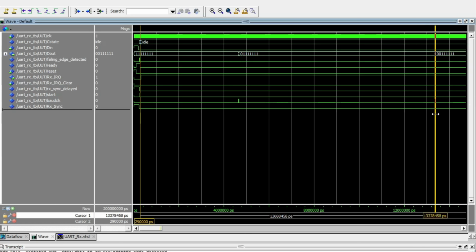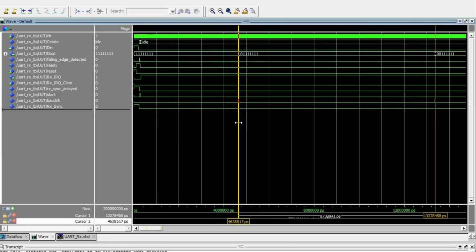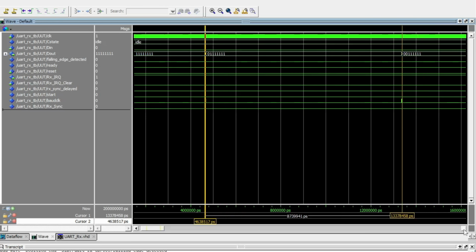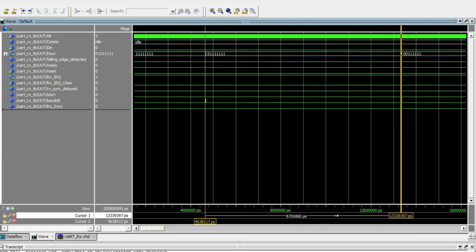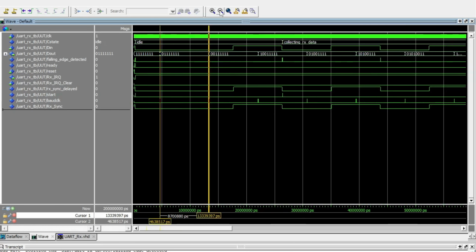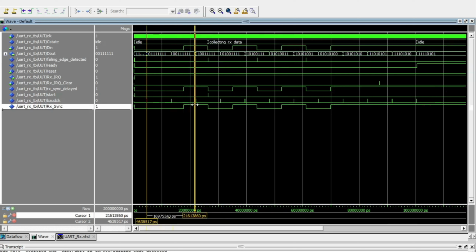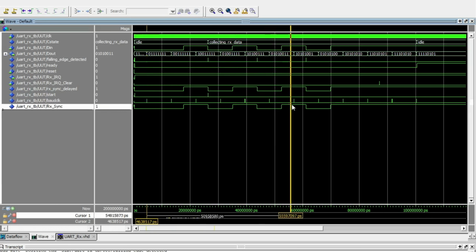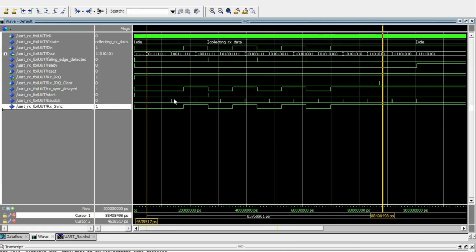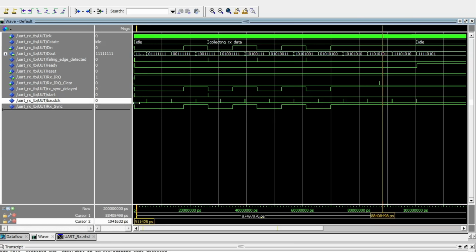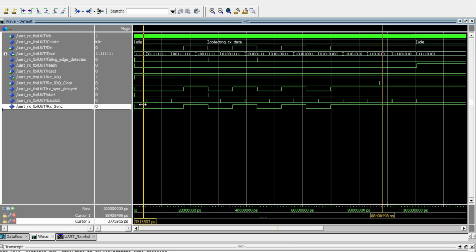So let's move this marker here. That should be near around 8.7 microseconds. You can see that we are around 8.7 microseconds, so this is one complete bit period. All the successive pulses look to be at 8.7 microseconds, right? These gaps are identical. Every gap is identical except the first one, because the first one is half of the bit period.